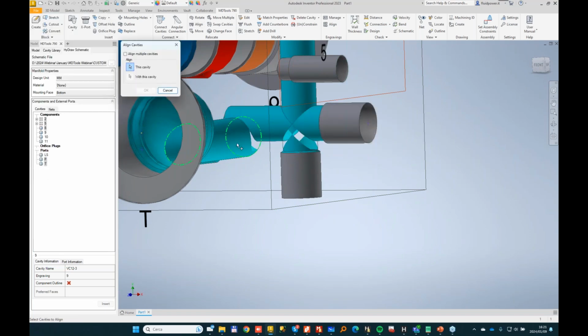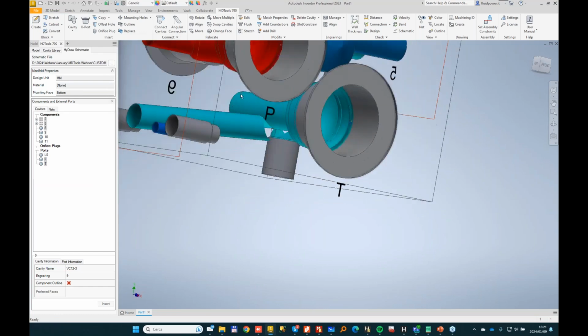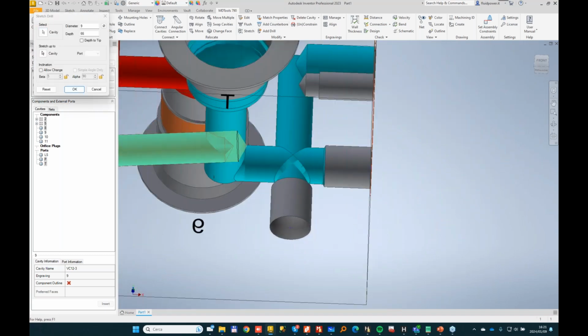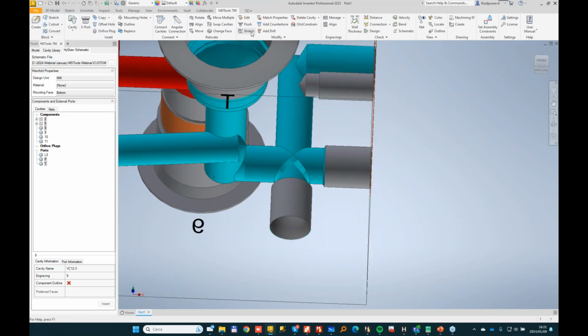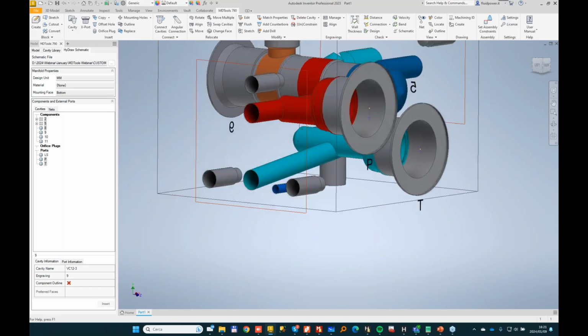In this case, I can align these two cavities. Center to center intersection is always better when possible. So in this case, the drill is not well centered, so I'll just add slightly, maybe 8 degrees inclination, and that's it.